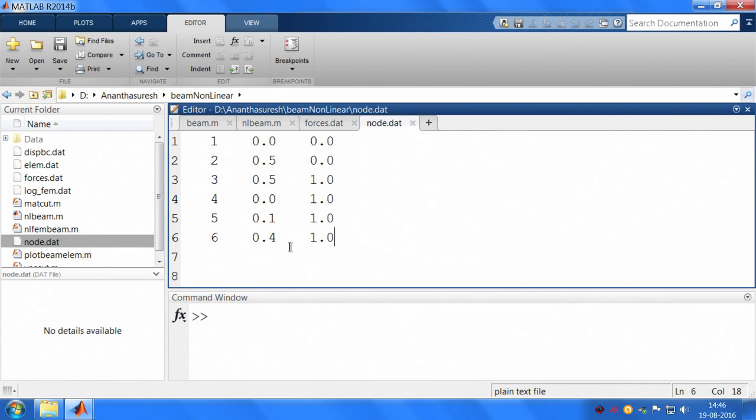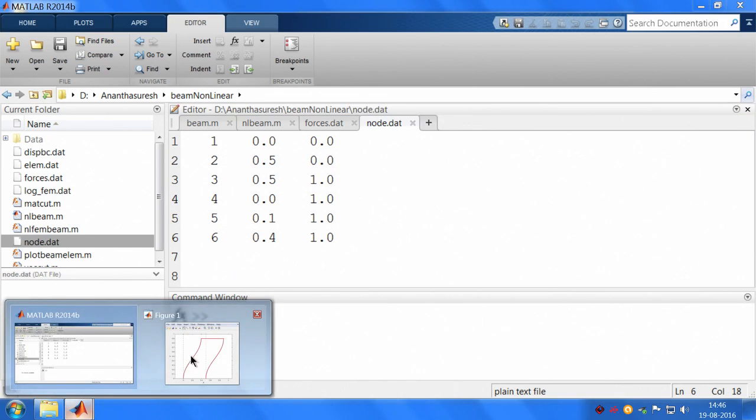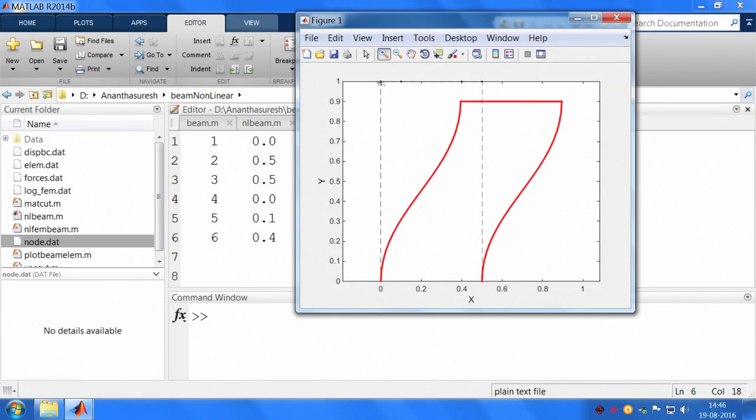So I am going to add 7, 8, 9 at the bottom, that is, let us look at the figure. So I have this original one, I am going to have 3 more nodes here, one here, one there, so that I can have this vertical beam and 2 rigid blocks. So the center I will have, that becomes a stage now, that becomes our moving stage, which is supposed to have purely x motion and no y motion, because we see that this top stage cannot have purely x motion, it has y motion, right.